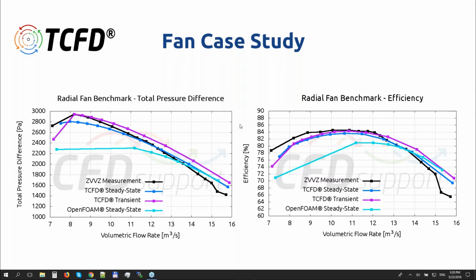because we put lots of emphasis on accuracy. So this one is on accuracy. It's a benchmark which we simulated in collaboration with Czech fan maker ZVVZ Machinery. This particular project was aimed at comparison of standard OpenFOAM and TCFD with a real measurement of a real existing fan. The case was a radial fan with very complicated airflow.